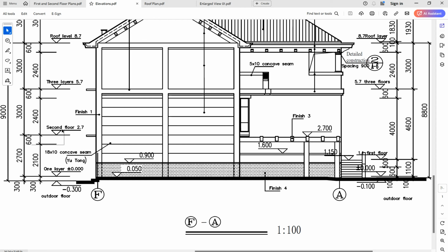So same thing, I have to double check on these drawings, which is like the third floor is 5.7, you can see 3.7 and 3 meters. So from second story to this one is 5.7. So it's easy to calculate. So you don't have to worry. You just click here. You just click this number, 5700 is already correct. And also the same thing. This one is 8700. So you can put 8700. So all will be correct.